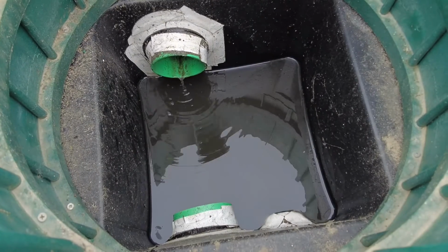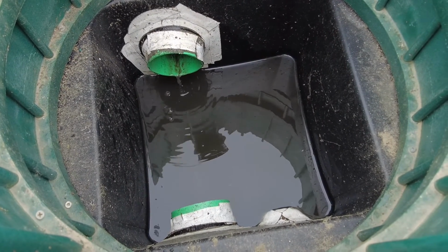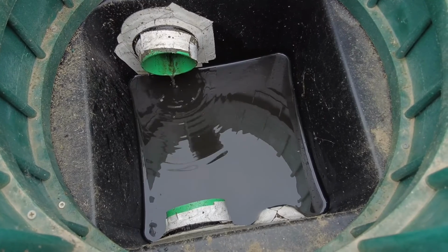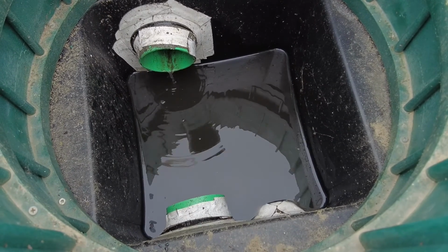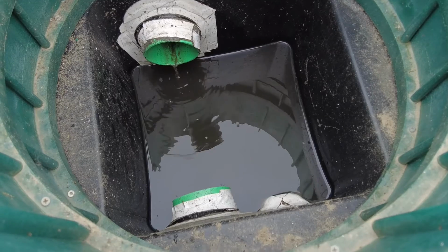So these are things like a distribution box before the leach field. They should be designed such that they're easy to get at and easy to get a free flow sample. I've seen instances where they design the D-box and somebody dips down into the D-box or pumps out of the D-box and gets sludgy stuff that's been settling there.